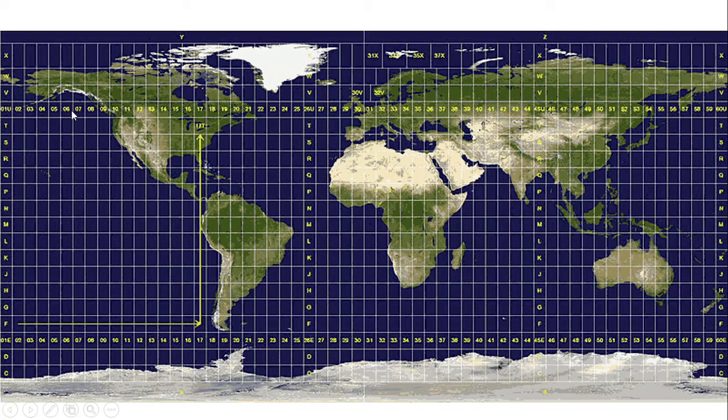The UTM coordinate system divides the Earth into 60 zones vertically. Each zone covers 6 degrees of the Earth's surface. Zone 1 starts at the 180 degree meridian. Each zone is again divided into northern and southern hemispheres. For defining the projected coordinate system, we need to understand the UTM zone in which our data falls.